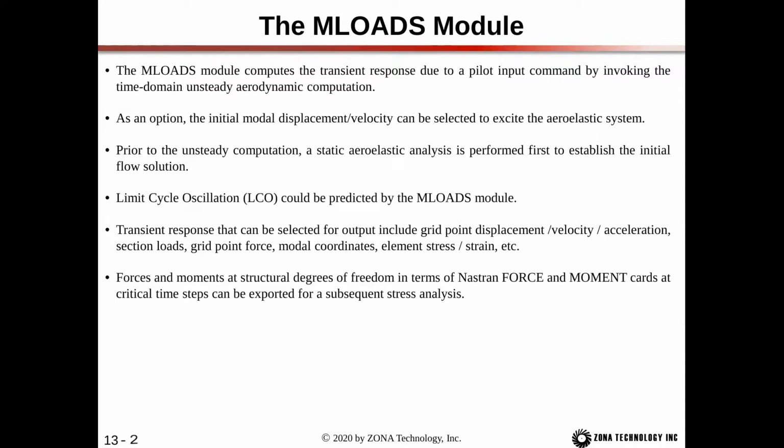Also, the transient responses that can be selected for output include the grid point displacement, velocity, or acceleration, section loads, grid point forces, modal coordinates, element stress or strain, etc. And the forces and moments at the structural degrees of freedom, in terms of Nastran force and moment cards at critical time steps, can be exported for subsequent detailed stress analysis.